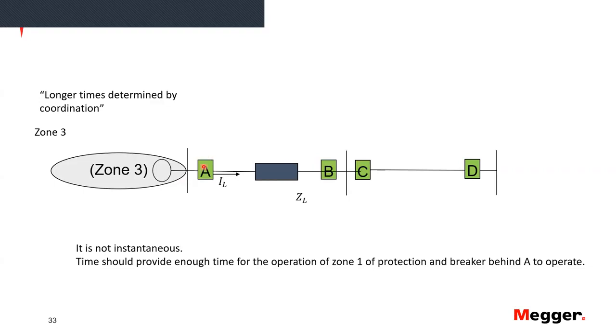Now, we've come here to the realization that distance protection should be directional. In distance protection, it is very important to know the direction where the fault is happening. It should know that if the fault is happening here, the fault is behind me. It should know if the fault is happening here, the fault is ahead of me.